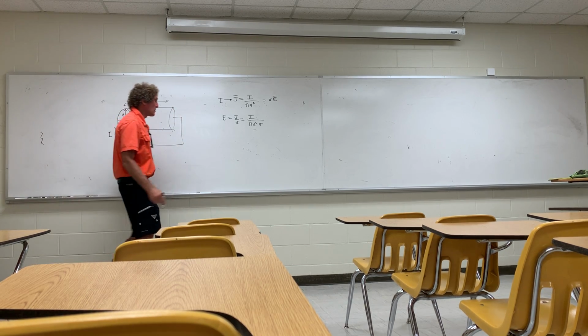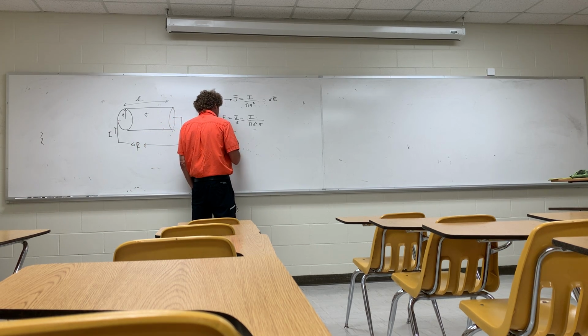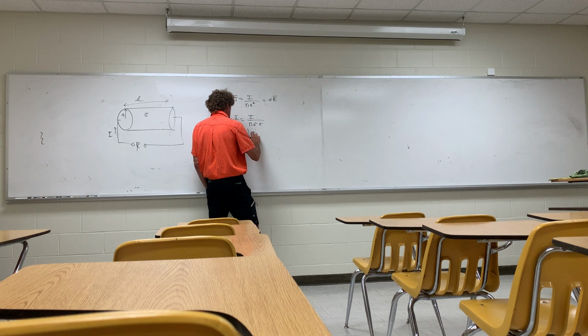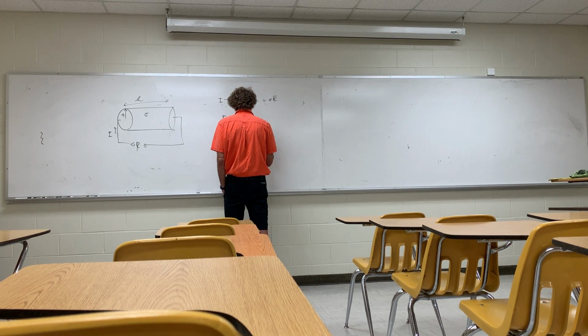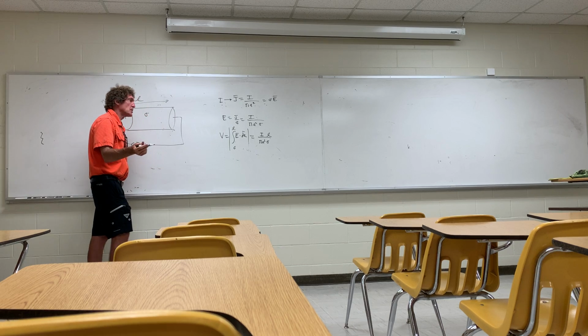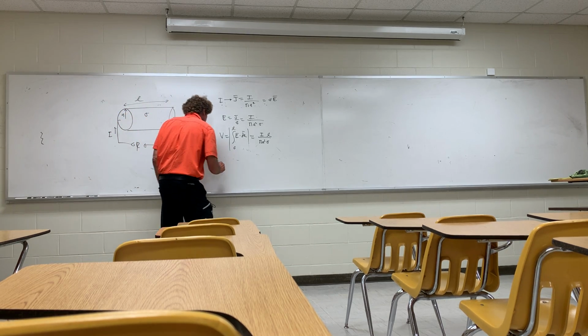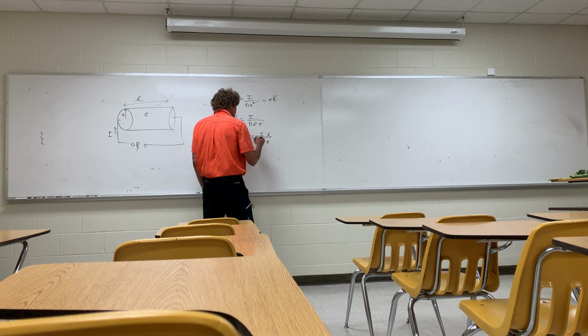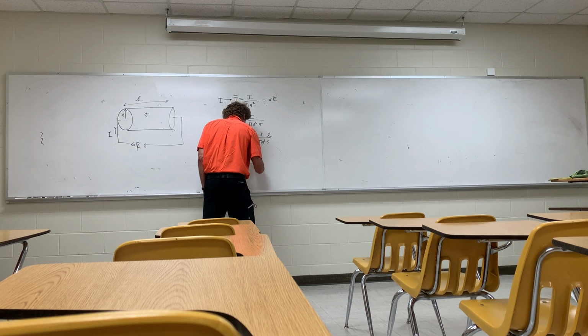Remember doing this? The voltage itself you can do as a magnitude integral over the length from 0 to L of E dot dL. And that's really because the E field's a constant. It's just going to be equal to the actual value of the E field, which is I over pi A squared sigma, times the length L. So now I've got the voltage, I assume current, I end up with the voltage, then I get the resistance R, and R is equal to voltage over current, and you can see I just get rid of the I, and that means it's L over pi A squared sigma.